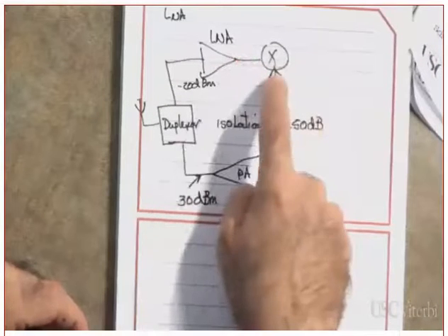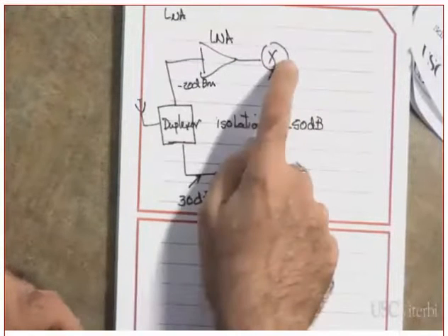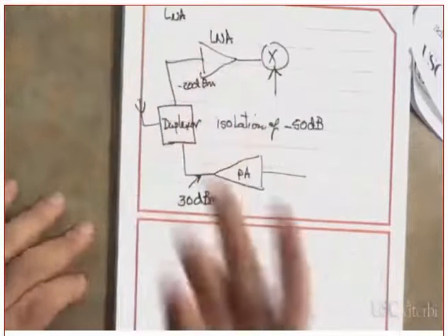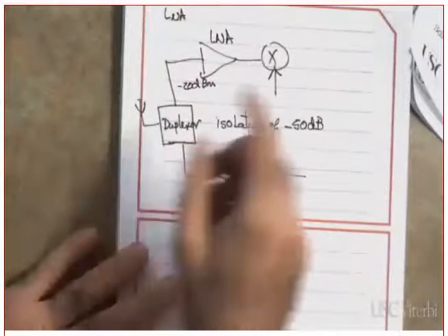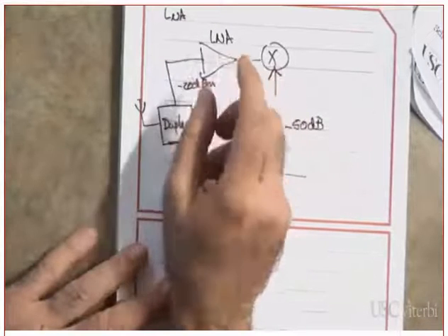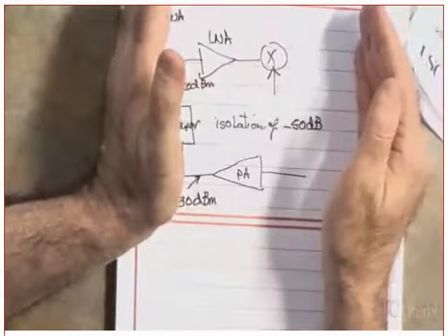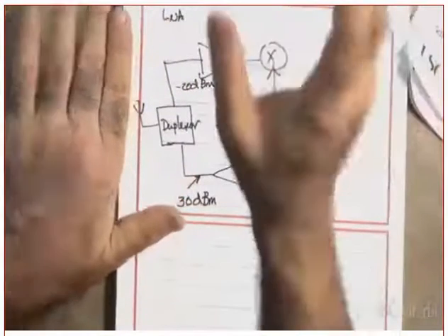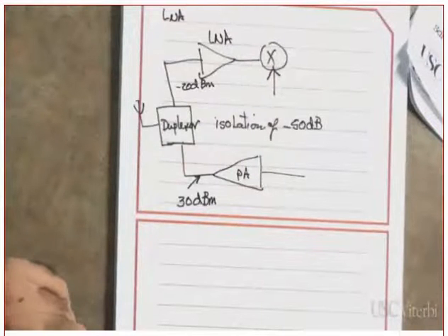And this 0 dBm might result in driving this into compression. And when you go into compression, it means that you will generate the third order intermodulation, all of these distortion components that we talked about earlier. Clear? So you need to be careful with designing the gain of your amplifier. You have an idea about what your overall gain of your receiver should be. Instead of concentrating it in one block, try to distribute it over multiple stages of your receiver.